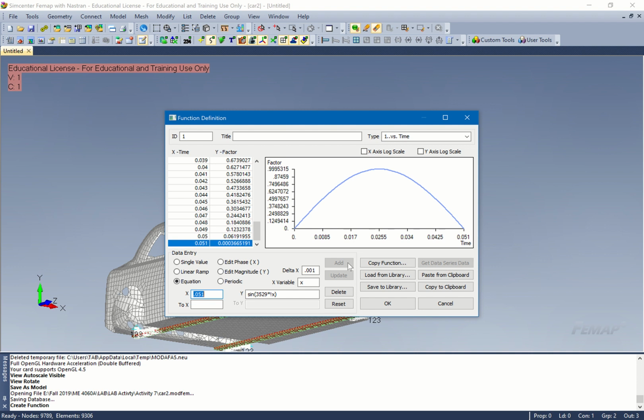Now, normally we put that as an analytical function time delay, but we're not gonna do that because that's not really supported as well. So that looks pretty good except for one thing. This is a very short duration, right? When it gets over to here, it will take these last 2 points and extrapolate based on the last 2 points for the next time step. So we have to make sure it goes to 0.